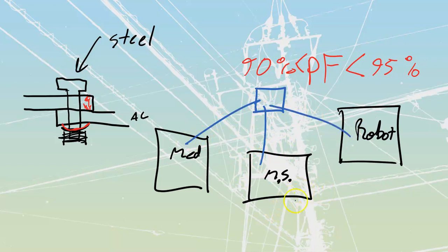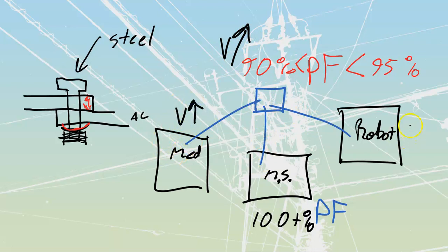And what could happen is you've got a poor power factor, and instead of properly sizing it, you just buy a ton of used capacitors off of some surplus site. You place these all in, and as soon as you bring this to over 100%, so 100+% power factor, the voltage on the transformer they're attached to is going to rise. So my voltage now goes up. Because this is the transformer I'm connected to, and they're also connected to it, their voltage is going to have risen as well.